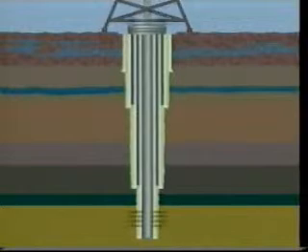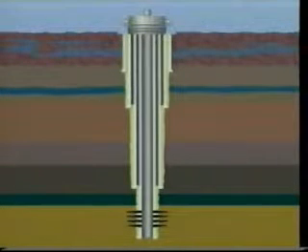This casing is perforated to permit production or set above the pay section in the case of an open hole completion. Because the casing head is attached to the surface casing string, it must be capable of withstanding the pressures encountered during drilling until a second casing string is run. The casing head must also support the weight of the subsequent casing strings and wellhead equipment, and it also allows the intermediate string to be centered, supported, and sealed.